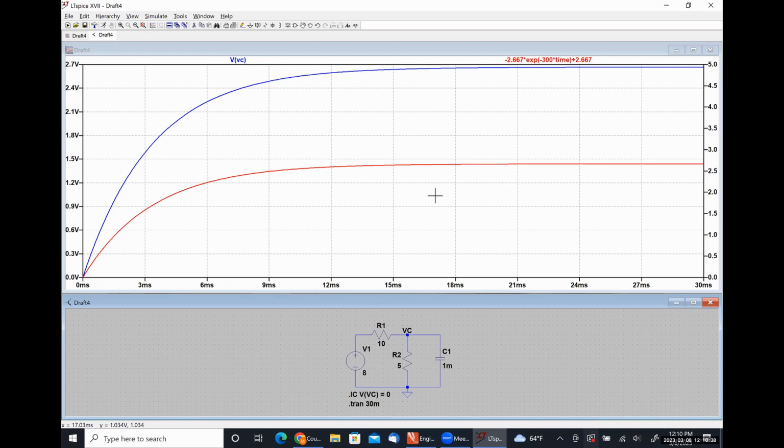There are a couple of other nuances that we're going to have to deal with. For instance, LTSpice does everything in degrees, not radians. And so we usually express angular frequencies in radians per second, which means we're going to have to add a conversion factor of 180 over pi. LTSpice also does everything with a sine function as its reference. And we have all gotten into the practice of doing everything with a cosine function as a reference. So we're going to have to remember to subtract 90 degrees and all that kind of stuff. But we'll get to that later.